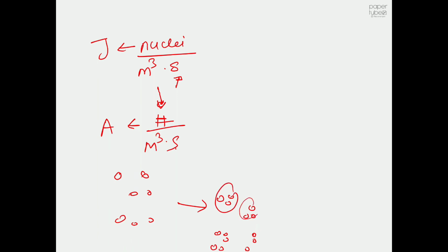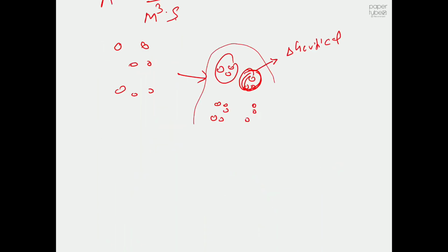When each of these pre-nucleation clusters reaches the critical free energy, then they will evolve into a stable nuclei. So this is related to the number of nuclei formed per unit volume per unit time, but A is a pre-nucleation stage quantity that describes how many molecules come together to make some number of clusters which may evolve into stable nuclei. So both have the same units.